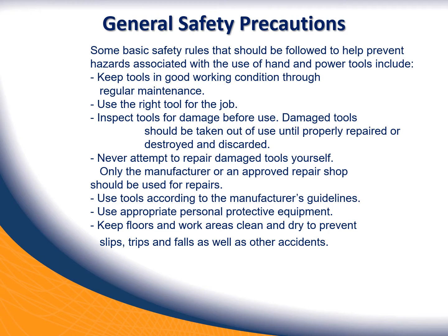Don't try to repair a damaged tool yourself. Take it to the maintenance area and see if they can repair it or just get a new one. Make sure you use proper PPE whenever you're using a tool, and make sure the area that you're working in is clean and dry so that you don't slip or trip when you're using the tool.